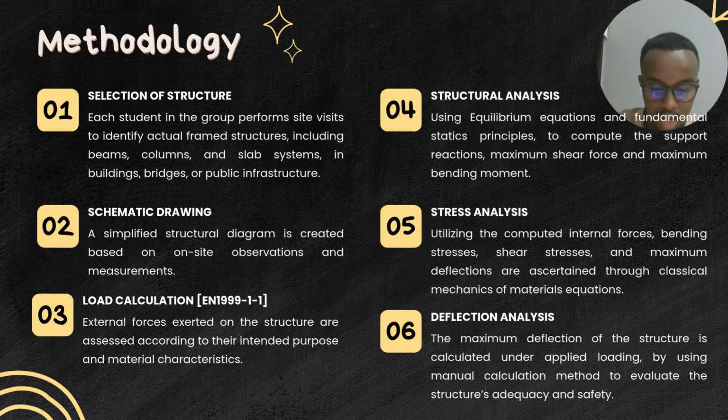Fifth, stress analysis utilizing the computed internal forces. Bending stress, shear stress, and maximum deflections are ascertained through classical mechanics of materials equations. Sixth, the last one, deflection analysis. The maximum deflection of the structure is calculated under applied loading by using a manual calculation method to evaluate the structure's adequacy and safety. That's all.